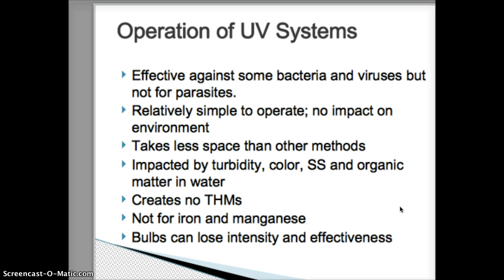The most important maintenance procedure is to keep the lamp clean and replace it on a regular schedule so the minimum intensity required is always maintained. Some UV systems may be equipped with a shutdown switch if the lamp intensity drops too low. This would concurrently shut off power to the well.